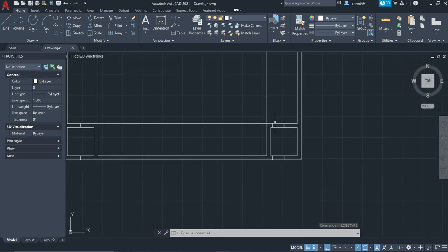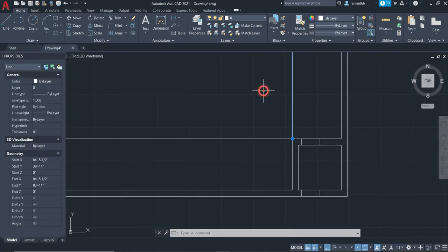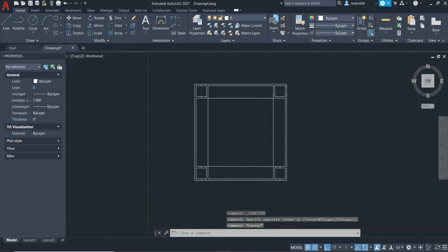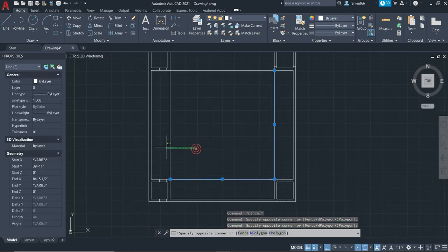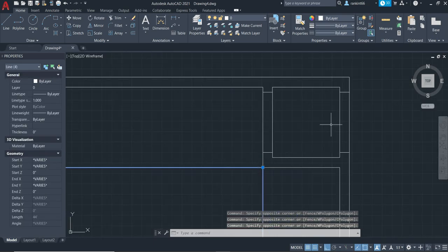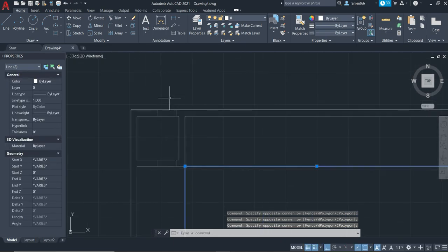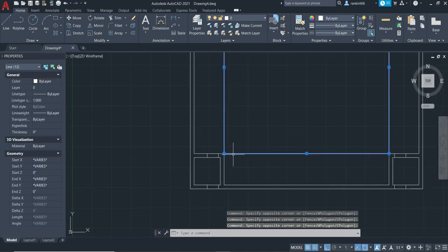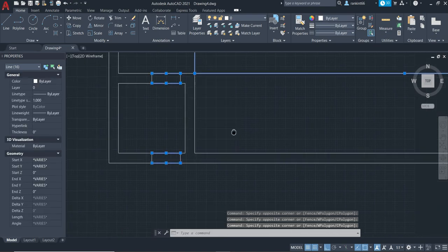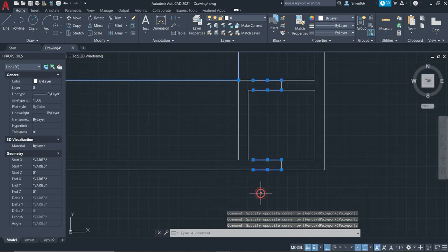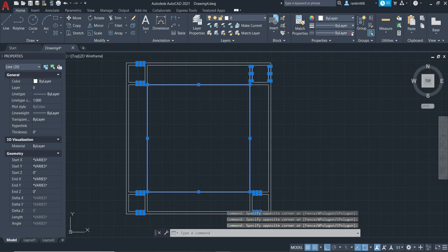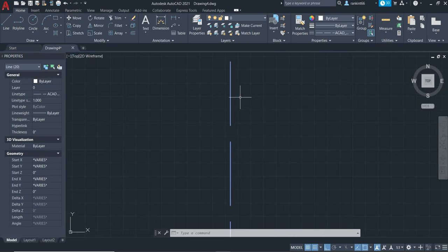So it deselected all of my lines and didn't apply it onto them, you can see here. So we'll just have to repeat that again. I'm selecting all those lines, going around really quickly and trying to click on all of them so that I can change all their line types together. Great. Now when we hit this drop down, you should notice that the dash line is there. If we click on it, now all those lines have dashes.